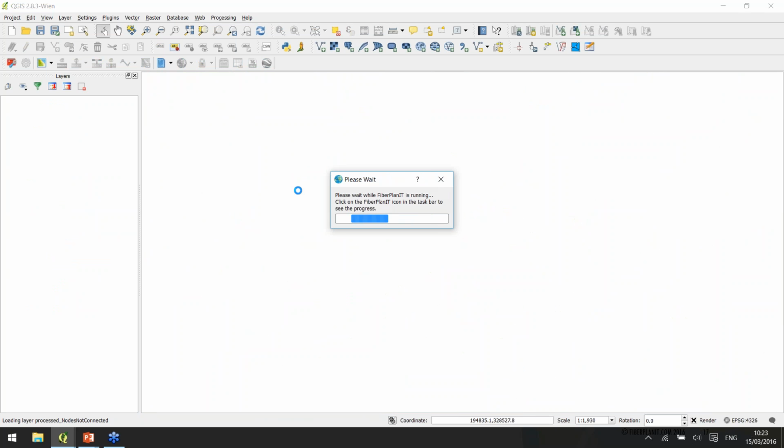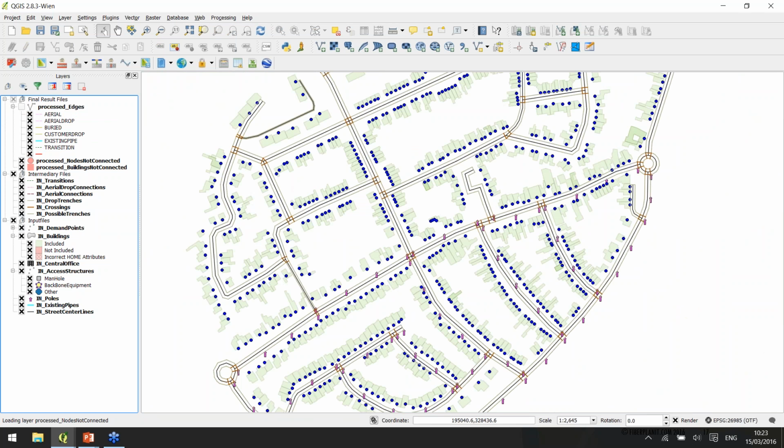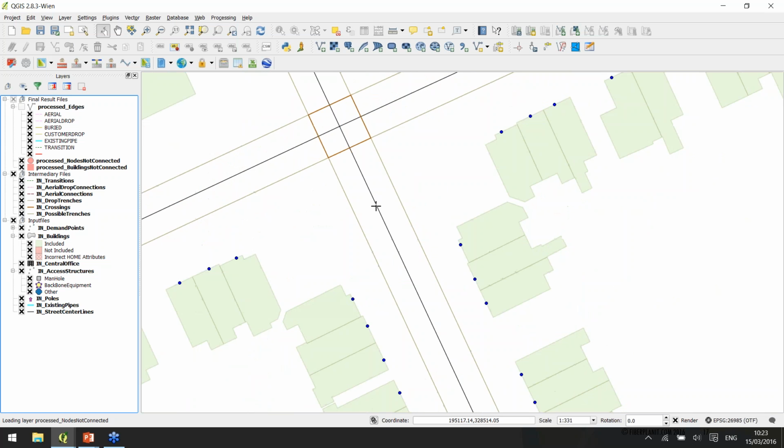To start doing your design, you can use the automated pre-processing steps. First of all, we will determine where the software can place cables and routes cables and ducts underground. So based on the street center lines, the software can calculate any possible trenching locations by the side of the road.